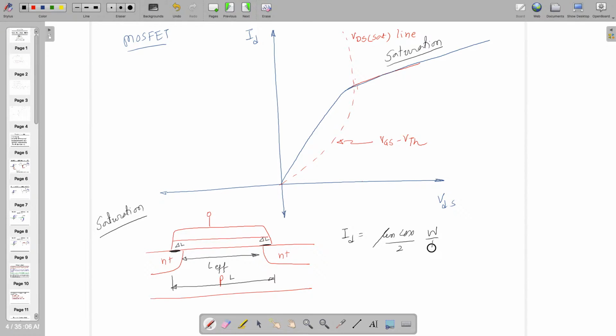And in this case, the equation looks like this, where there is no control from drain to source. In this equation, there is no drain to source voltage, right? And that's why some of our parameters, y12 and y22, become 0, because this was del IB by del VCE, and this was del IC by del VCE.